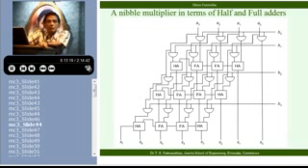Take a byte, take the other byte, do the partial product, store it somewhere. Again, take 2 bytes, store it somewhere. You just go on doing it and then do a repeated addition. Sequentially you carry out partial product, summation, partial product, summation. That will call for additional time. Time-wise, it will take more time, but less area.